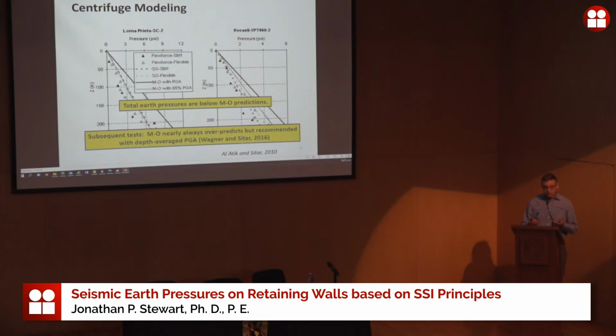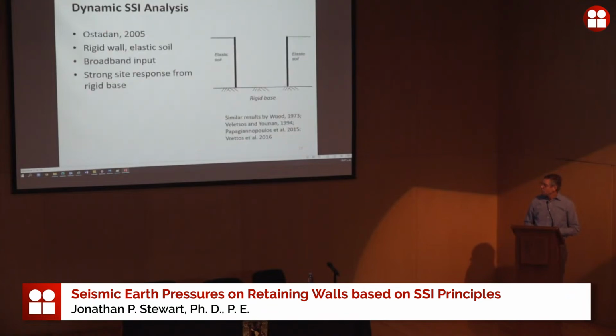So that's trying to come up with something that is customized for each ground motion. Okay, so again, let's keep in mind that when we look at tests, the limit state methods overpredict. We can try to put a Band-Aid on it and fix it in different ways, but they tend to overpredict in just their natural state.